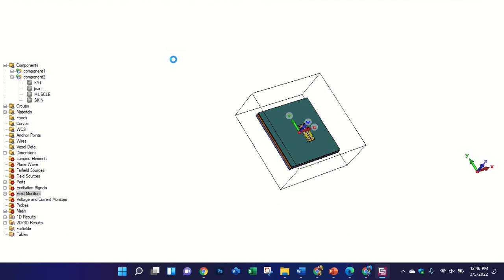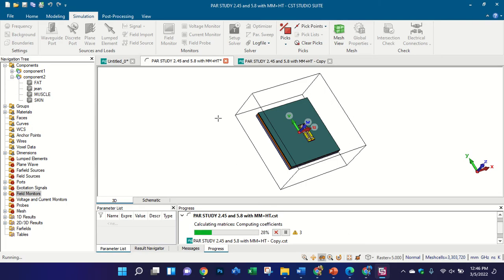Mr. Ahmed, can I reduce the mesh size? Maybe if we reduce the mesh size, we can save time. If you decrease the mesh size, then surely it will not take much time in simulation, but your results will not be acceptable when you fabricate your design and test it in measurements. It is not accurate. I do not prefer to keep a small mesh size.